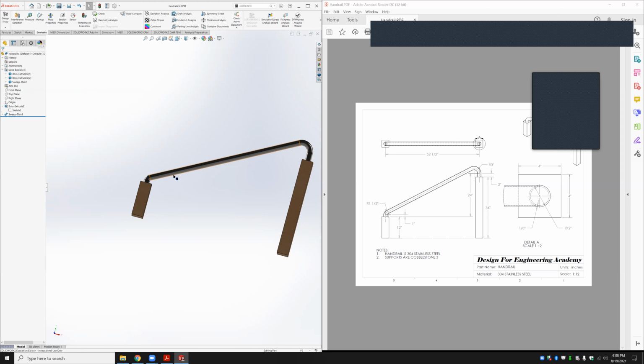Yeah. Another way that you could do this too, I wouldn't suggest this, but just so you know, another way. I think that you would have no problem doing that. If you remember, before we made planes with reference geometry. So one thing you could do is, if you pick for your first reference this surface, and for your second that surface, you'll get a plane bisecting those two right in the middle.